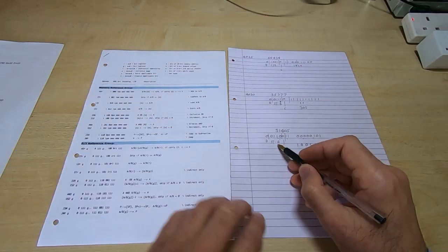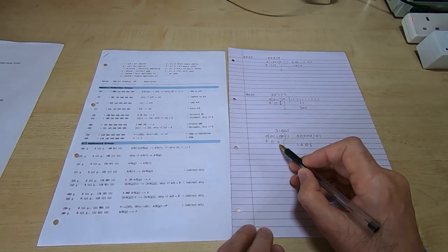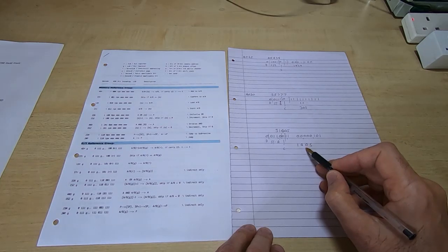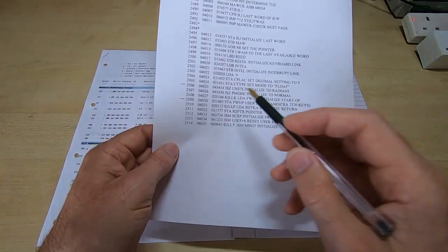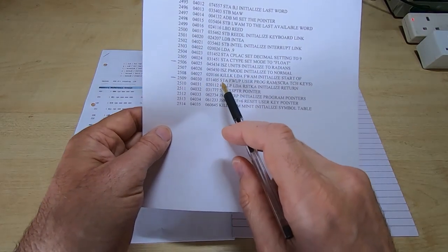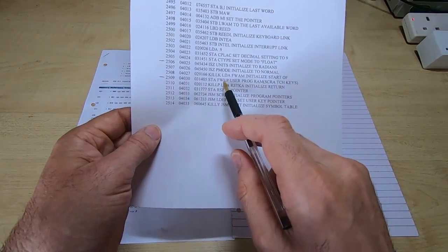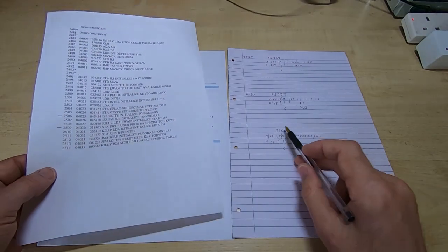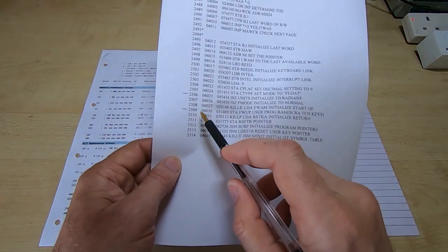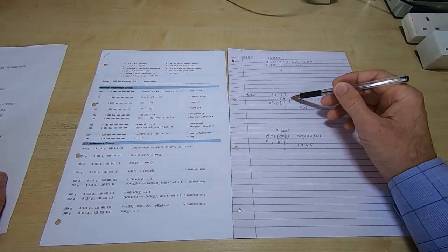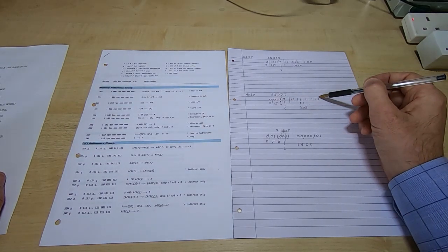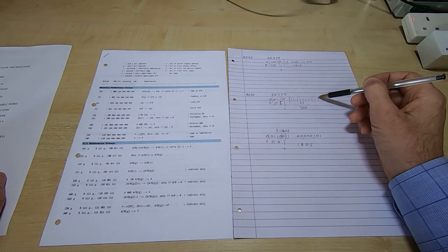So in other words, we want to store the value in the A accumulator at this address, and does that match what we're trying to do in the code? And as you can see, it's a store A at this address, which exactly matches what's in the listing, but does not match what we captured. Also, the fact we're getting all zeros from this address tends to concern me.